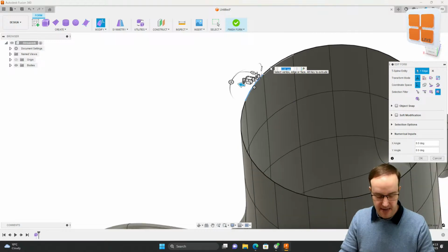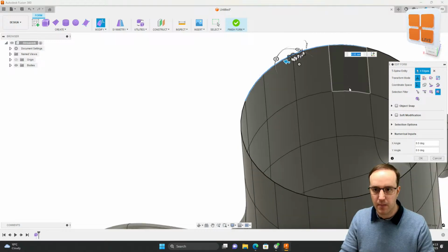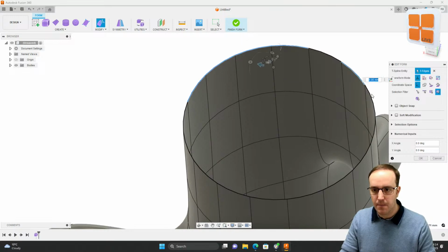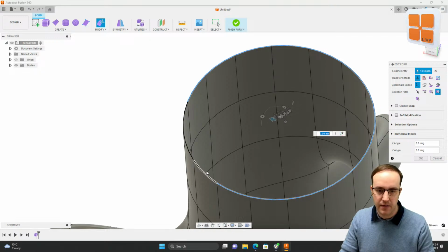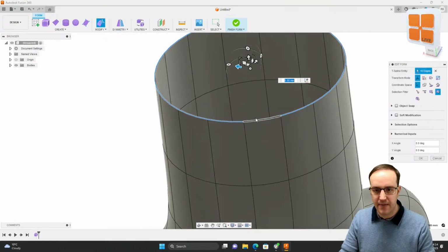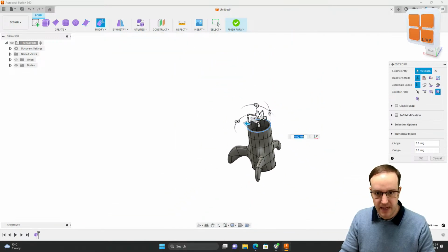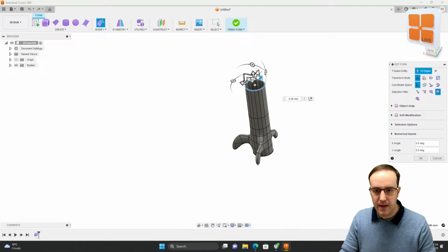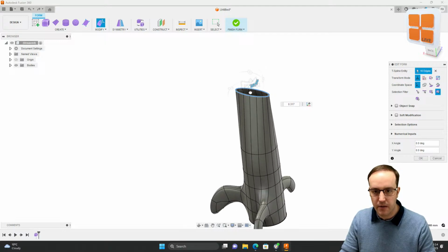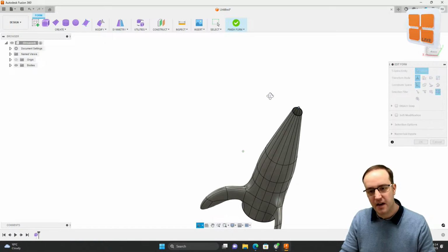So I can go ahead and select all of these components that build up the top perimeter, if you like, of this shape, and we can then extrude those up and bring those in to a point. So we're going to come and select all of these around the outside, zoom out a little bit, hold down Alt, go upwards, and then I can basically grab them and scale them in. My eyes are terrible today. There we go. Scale them in this way, scale them in this way, and I can basically start creating this kind of point shape. I can then start patching holes.